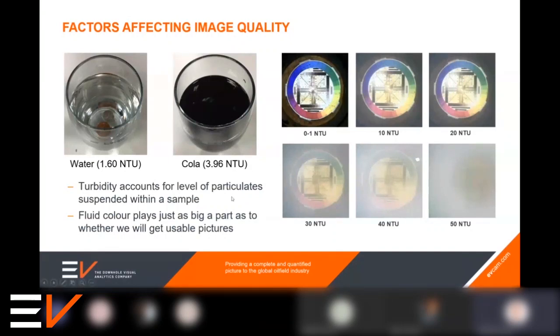But again, we'll take a look at what is likely to be in the well. We'll look at the access to circulating the well. It could be that even shutting it in, if there's free gas or produced water, we might be able to position that column so that we've got the clear medium in the place we're interested in recording.